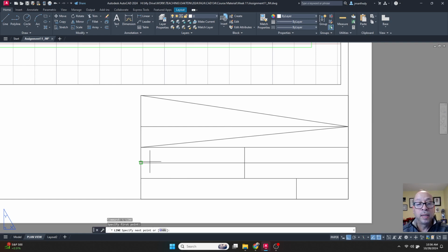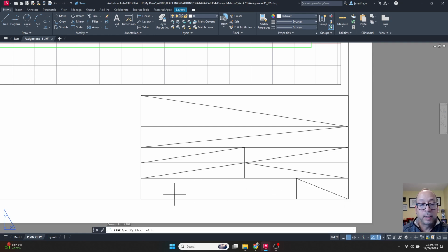So I'm going to draw a line and create a little guideline here. Let's do another one here. This one will be empty, but I will locate it here, and I'll draw another guideline over there. There'll be another one here, for example, and then the final one will be here, little triangle. So these lines will be used to snap to when I'm adding text. So let's do a single line of text for the title block, and let's place it on the screen here. Now, right here it says start point of text, where the text is going to start. Now, currently, I will snap to the center of this line, the midpoint of this diagonal line, click.